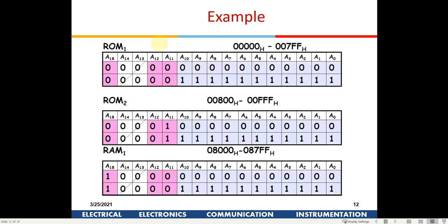Once you have done that, you make a table. These lines are going to be common, and the variation is going to come in these two columns out here, for the RAM and this value. You have to ensure that there is a unique address for each of the RAMs and ROMs. If you see, these are all 000 and this is 01.